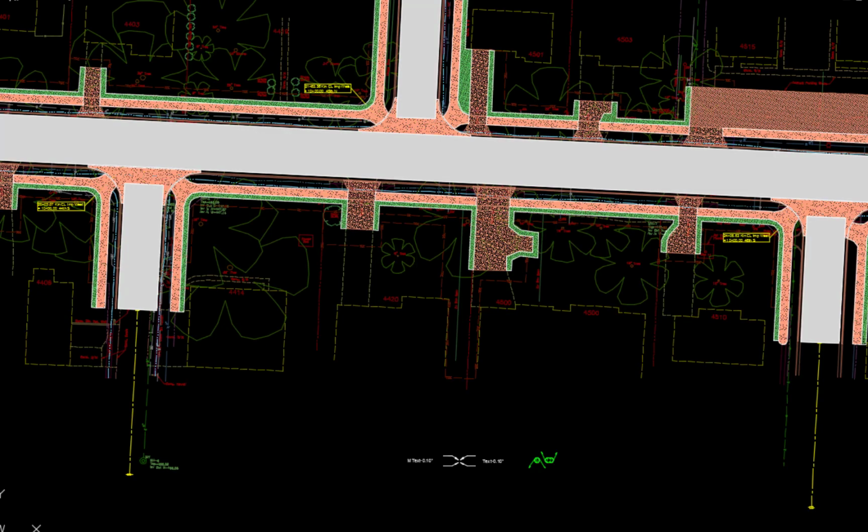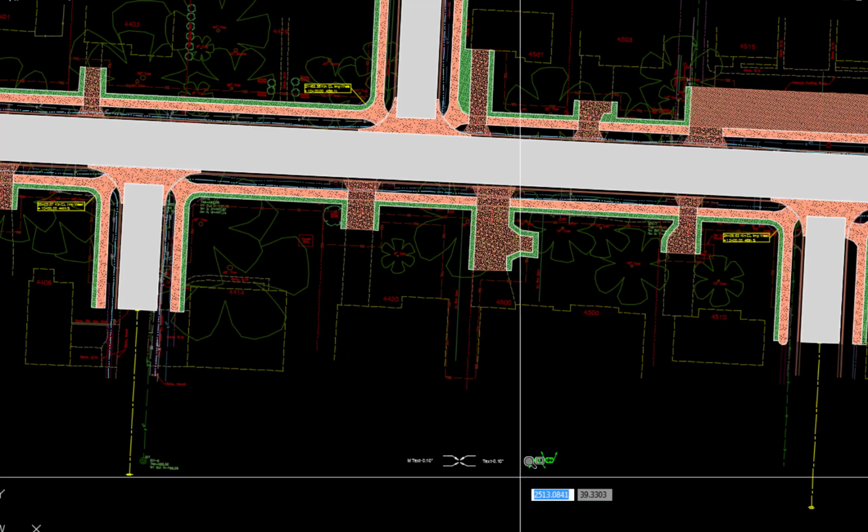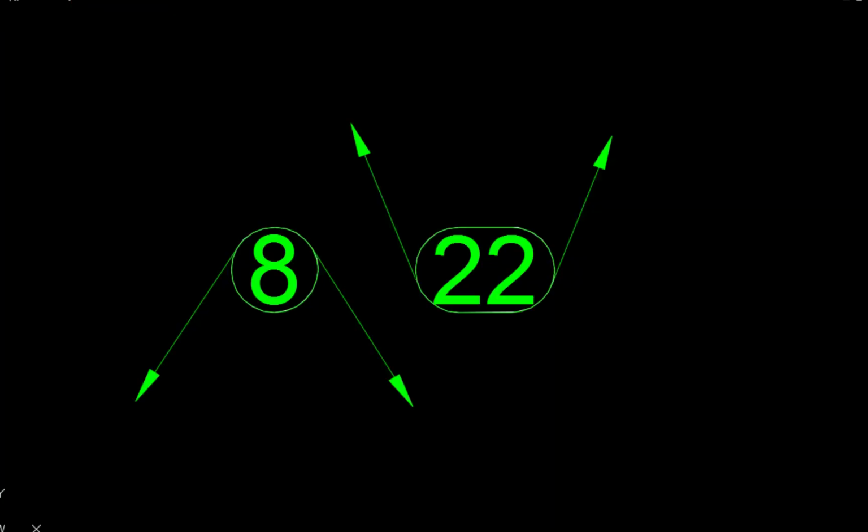In order to keep the drawing clutter to a minimum, Atkins uses construction reference labels that reference the corresponding construction note numbers and are placed in the vicinity of improvement objects throughout the drawing and are used in lieu of individual notes. With the reference label, there is a lot less clutter and more detailed instructions can be given in each construction note. The construction reference labels are on layer C road text and consist of a circle or elongated circle with 0.12 inch Arial bold number contained therein.